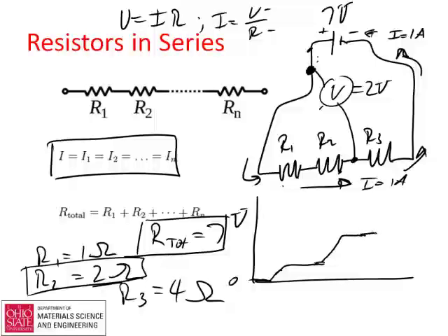And then when I pass R3, it would go up to 7 volts here. So I could take my voltmeter, clip it here, it'd be 0. Here it would be 1. There would be 3. And there I'd have the full 7, which would persist anywhere I'd put the clip all the way up to there.